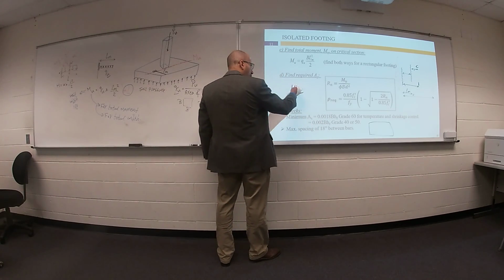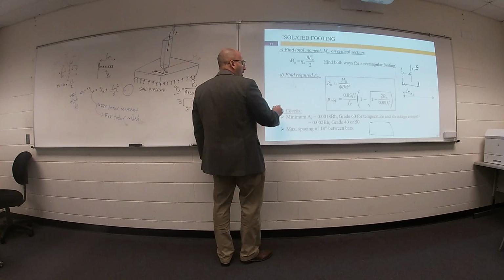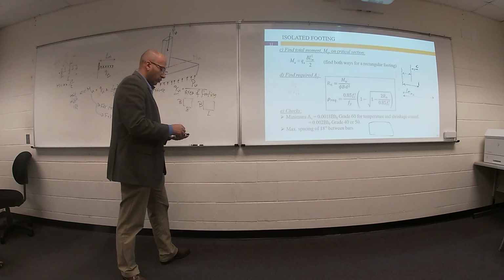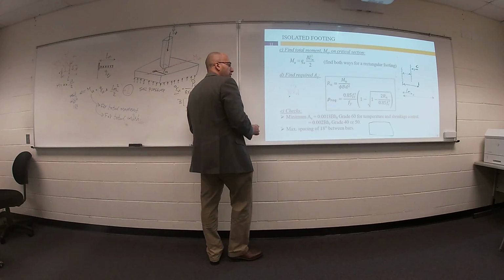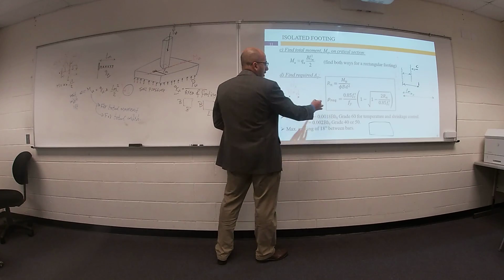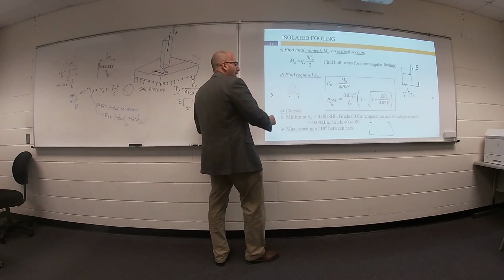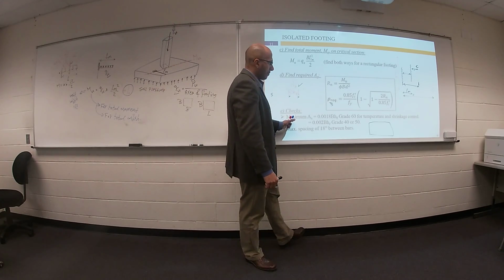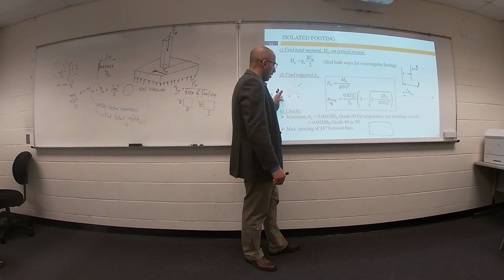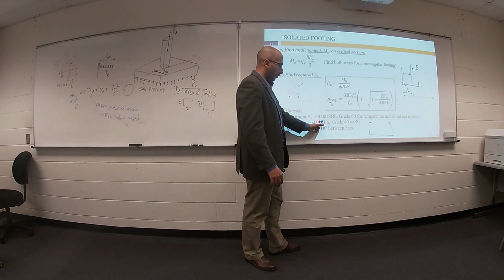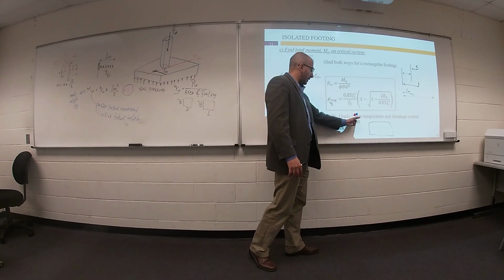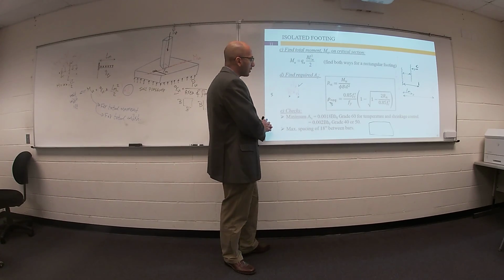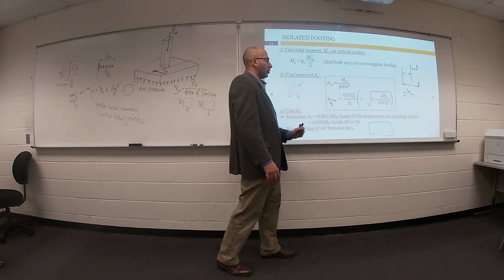The area of steel is rho divided by b times the depth of the footing. So I know the width of the footing and the depth of the footing. I now calculate the rho required, and I can figure out the area of steel. And remember, we have minimum reinforcement. This value must equal or exceed this value or this value, based on the grade of your steel reinforcement. Also keep in mind the maximum spacing between bars in a footing is 18 inch.